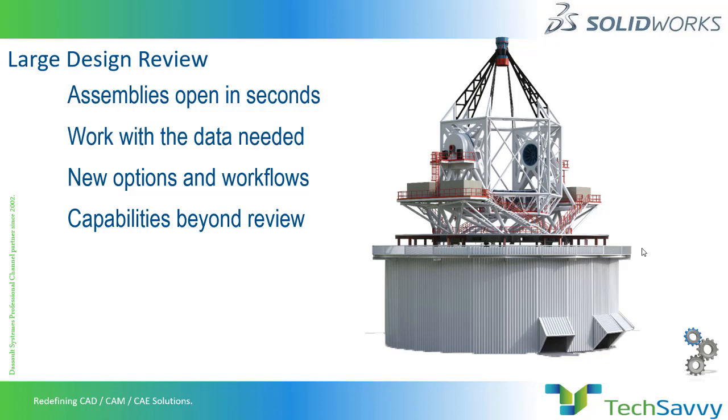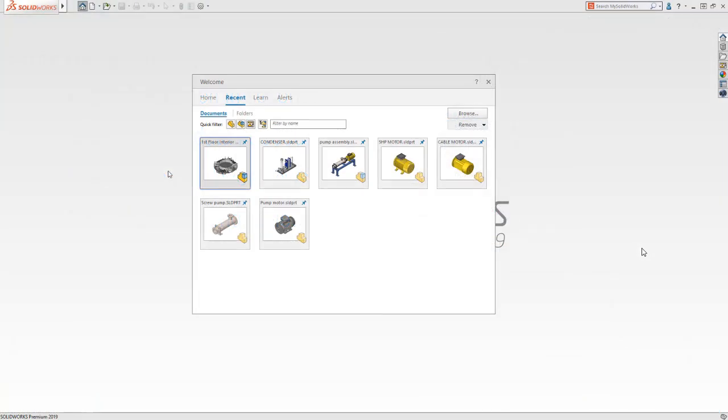Now with Large Design Review mode, we are doing lots of things like mating components, changing the configuration, cross sectioning, and all those things. So there are new options in the workflows, capability beyond just review. Previously, with Large Design Review mode, we were only able to review the assembly, but in SolidWorks 2019 we can use LDR to do much more than a review. So let me show you how we can do that.